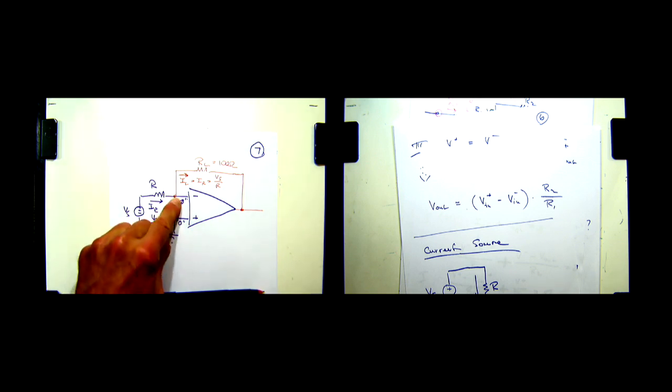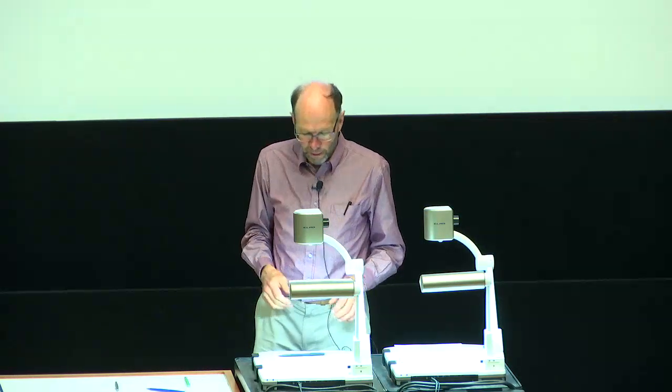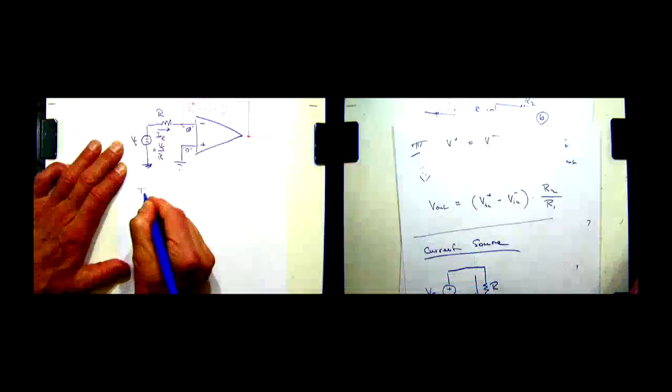The op-amp makes sure that that's the case, because it keeps this voltage here nice at 0. But the current cannot flow into the op-amp, therefore it has to flow through whatever we connect here. So this acts like a current source. The current in RL is constant. Precisely the definition of a current source. Now in our touch sensor we had a capacitor and we wanted a constant current flowing into our capacitor. Well, we just replace RL with the capacitor. So, touch sensor.